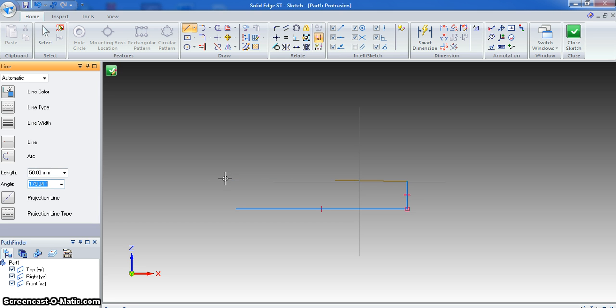See the lines continuing on from the last line. Now it wants to again snap to that reference plane, which is not quite 180 degrees, so I'm actually going to have to type in 100 minus 180 because it was a minus in front of it, and you'll notice that it won't snap to the reference plane. Instead it will do that angle 180 degrees. So if you ever are drawing close to the reference plane and it's trying to snap to the reference plane, try and avoid it and make sure you get the right angle and get what you want out of it.